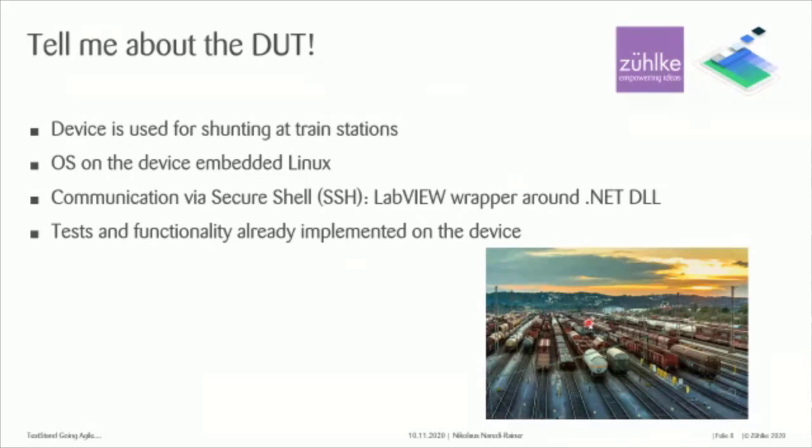And I talk to the device. So the device is being assembled. It is being put onto the end-of-line tester. The PC that commands the end-of-line tester then opens up a secure shell connection with a LabVIEW wrapper around the .NET DLL. You can imagine, for those of you who know PuTTY, for example, for communicating via SSH, I implemented something like that in LabVIEW and then was able to communicate with the device.